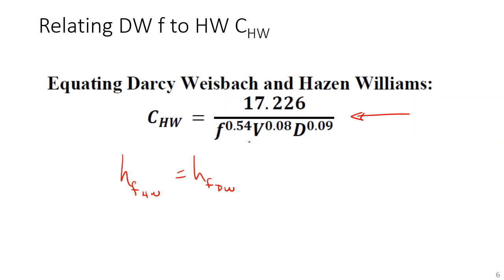And this is why the Hazen-Williams contours on the Moody diagram of the handout plot as diagonal lines. This is basically Reynolds number, velocity times diameter over nu is basically the Reynolds number. And so what's happening is the plot of Hazen-Williams on this Moody diagram is a sloping line. It's not a horizontal line.